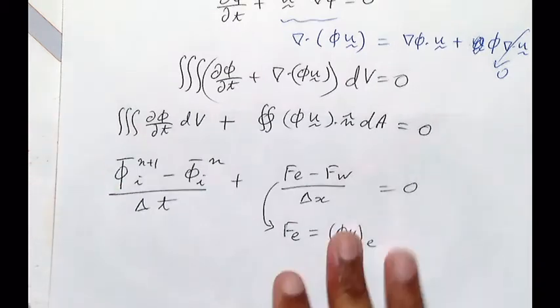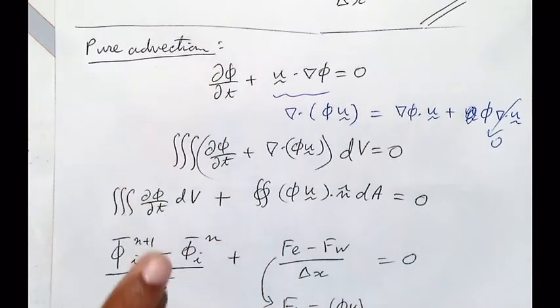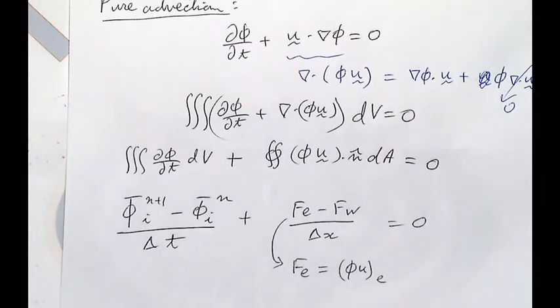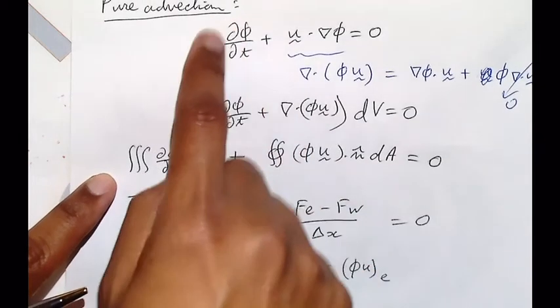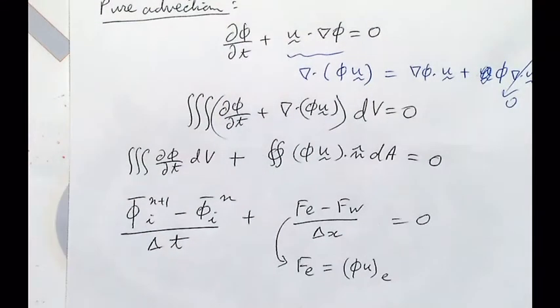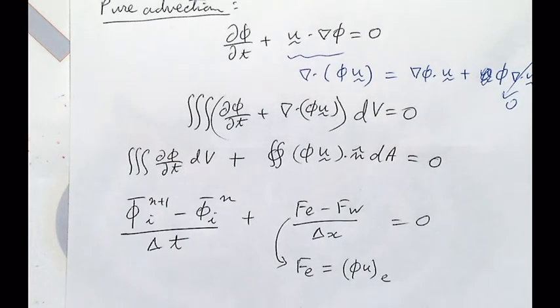At this point you should be very comfortable jumping from the PDE form to the integral form, changing to surface integrals, and how that goes to the finite volume form. This can be done for the advection equation, diffusion equation, advection-diffusion equation, momentum equation, anything. Luckily, most conservation laws we deal with come from conservation form because this is the basic law, this is how they're derived. Most of our equations are already in this form. Okay, makes sense?